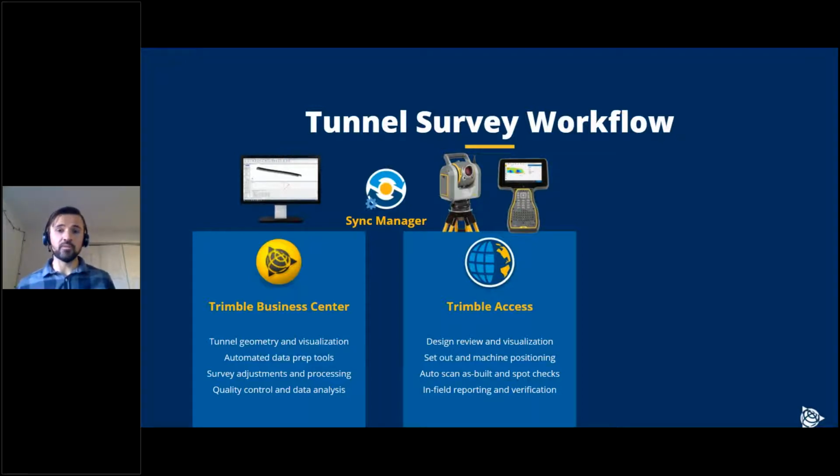One of the automated functions that I really like in Trimble Access tunnels is the automated as-builting, where we take the tunnel design and automatically collect the as-built profiles based on the values that the user inputs. And then of course, in-field reporting is huge. So not only is it collecting data, but it's also having that real-time feedback while in the field. Has the data I've collected, if we built the tunnel in the right spot, is the overbreak significant? Is there underbreak, so we need to excavate more? That kind of feedback while I'm in the field.